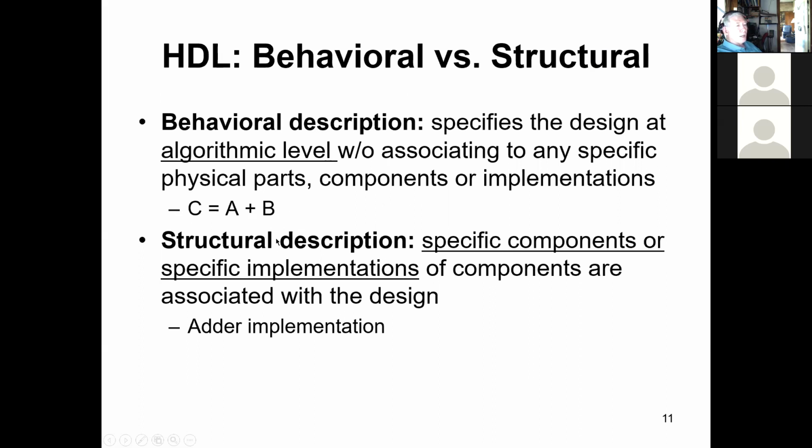When we want to actually get down to the structural level, now we're going to say, well, we're going to use specific components. Maybe our adder is going to be a carry look ahead adder. We're going to implement it as much as we can with AND gates or lookup tables or whatever we're going to do. So usually the design evolves from a fairly high level behavioral description to a structural description where we have to have specified some of the details.